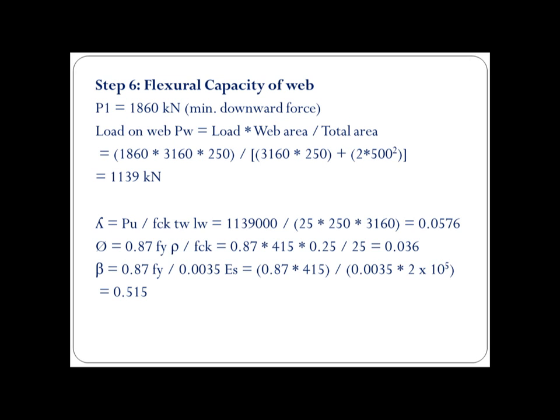Now in this case, since we have two boundary elements, one at each edge, we need to see that either the web can be exceeding the stresses, or it can also be less than the moment, so that the additional forces are to be taken by the boundary elements. Now we calculate based on equations given by IS 13920 Annexure A.